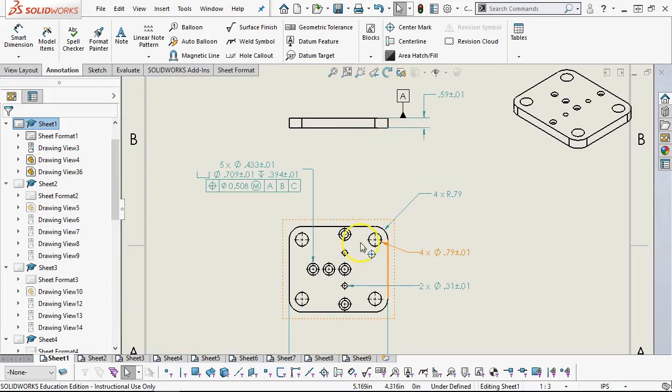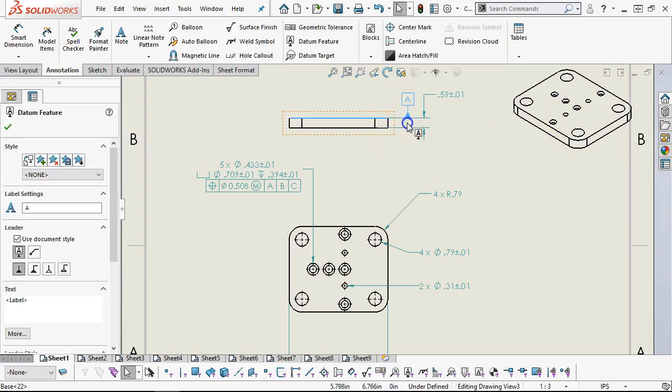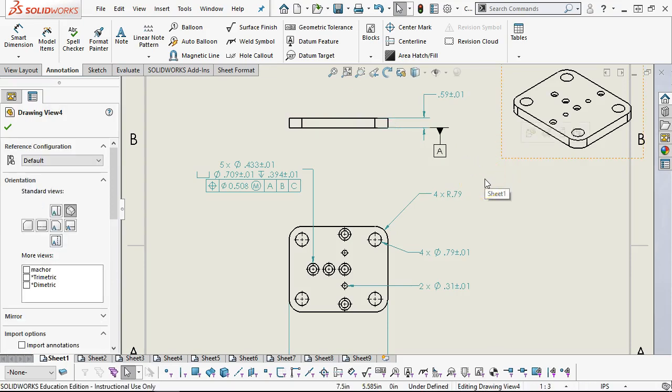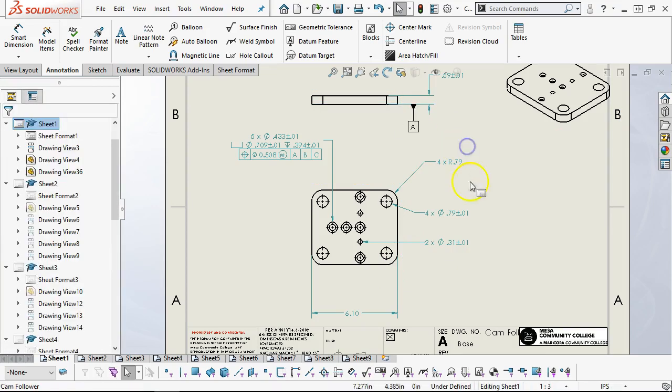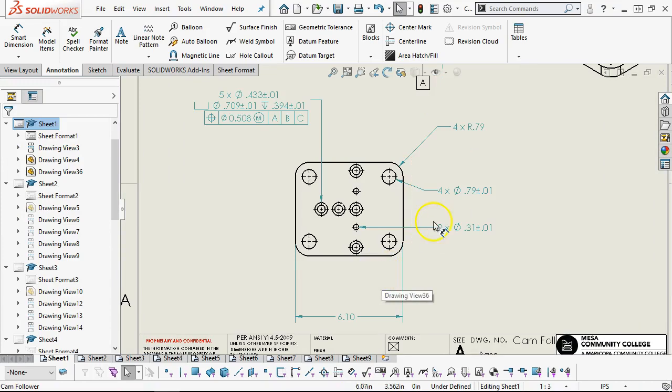And then the parallelism would actually be the back side of this part, because it will have the parallelism, but that is where the next vertical piece comes in and starts to build up and has that next contact. All right, so if I can grab that point and drag it out and away, I can always change my datums as I think through the process. Right, so until we get to a point where this is reviewed, that we've all agreed that that is an appropriate datum where we want to place it, the visual on it, we're able to make those adjustments.